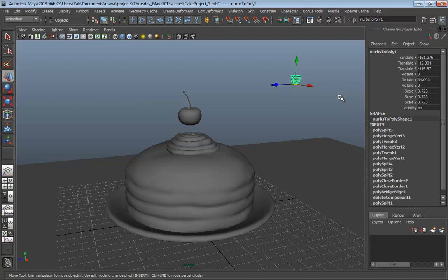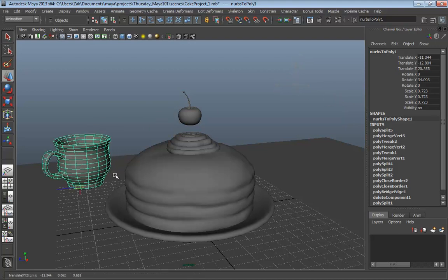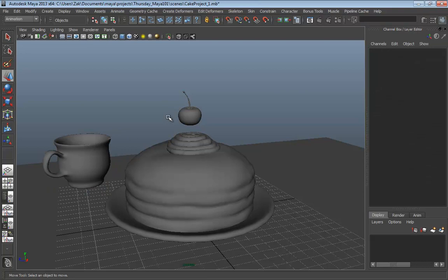Is there something like automatic LOD? Not in this case, no. So keep that in mind. Maya is going to take exactly the textures that you feed into it and send those off to be rendered. So at the end of the day, you want to keep those as tight and as efficient as you can within reason. Now, in our class here, for academic purposes, I'm just going to be handing you some very generic textures, and we're just going to drop those down. Those shouldn't be considered standards for any reason. A lot of that has to do with what resolution you're going to be exporting out to. Are you saving out to like HD? Are you just saving out to something like 640 by 480, etc. and so forth? A lot of things to think about.